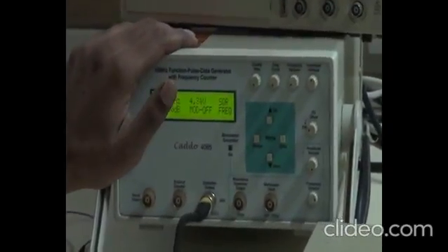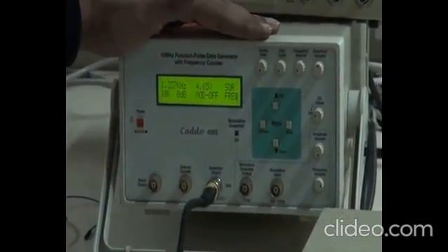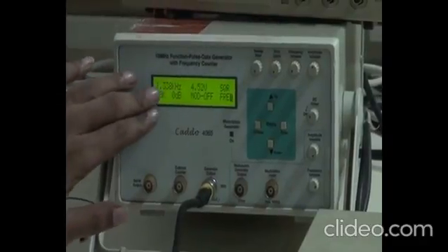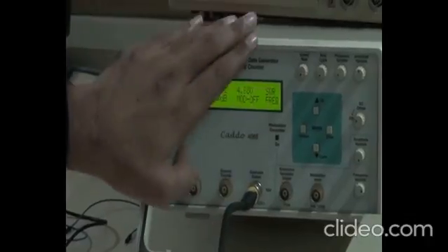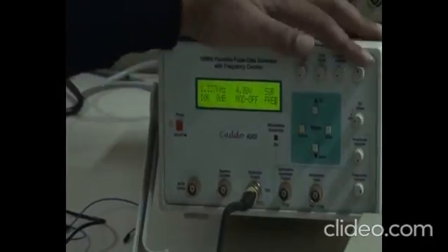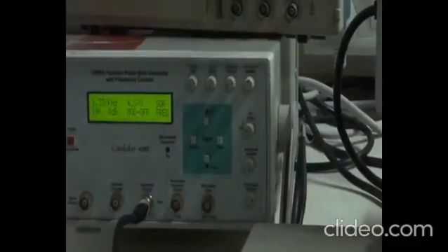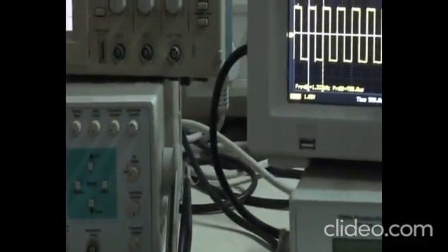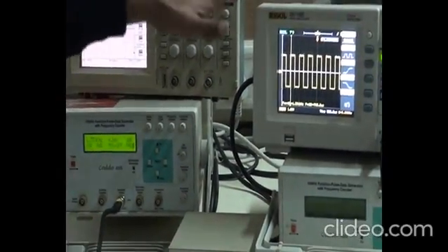So let's just see how. First of all, before you connect it to the breadboard, you have to generate the square wave from the function generator. Okay, so right now we have set 1 kilohertz and 4 volt square wave from the function generator. But you have to set this particular waveform, and you have to observe it on the DSO. Okay, so right now I have taken this input from the function generator and I have connected it to the DSO. So you have to verify that first.